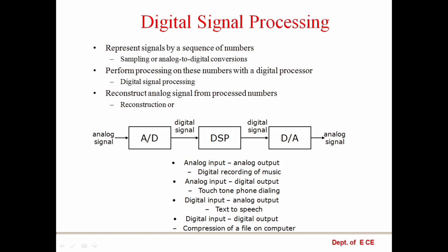The DSP processor system extracts the information from the ADC, and finally we give it to the DAC. The purpose of the DAC is to reconstruct the signals, so once again we get an analog signal. The same signals we give as analog input, we get in the output with the help of reconstructing filters. So here we give analog input and measure analog output.